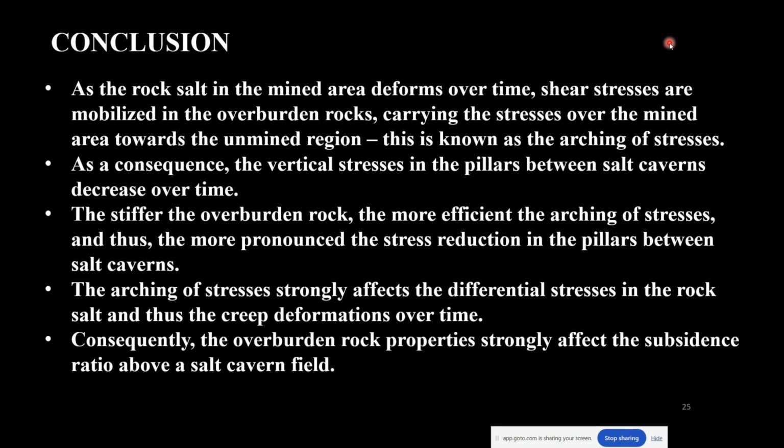This is not something obvious, and because they may strongly affect the deformation rates, the overburden rock properties should be carefully studied and selected as precisely as possible for proper geomechanical analysis of salt cavern fields.